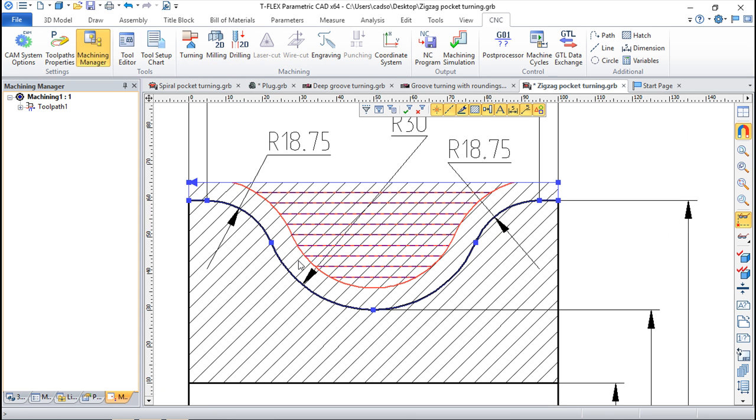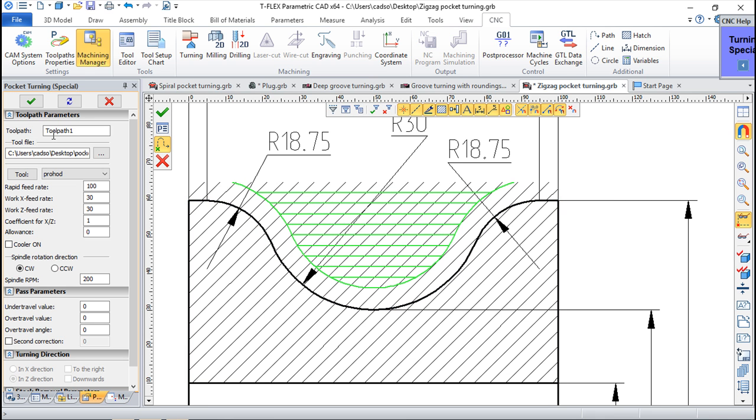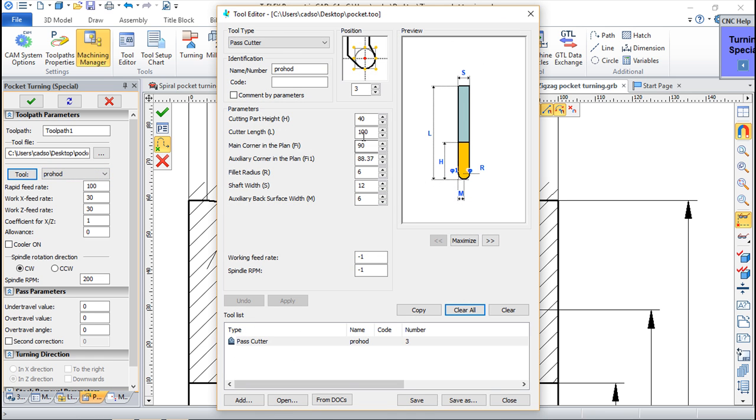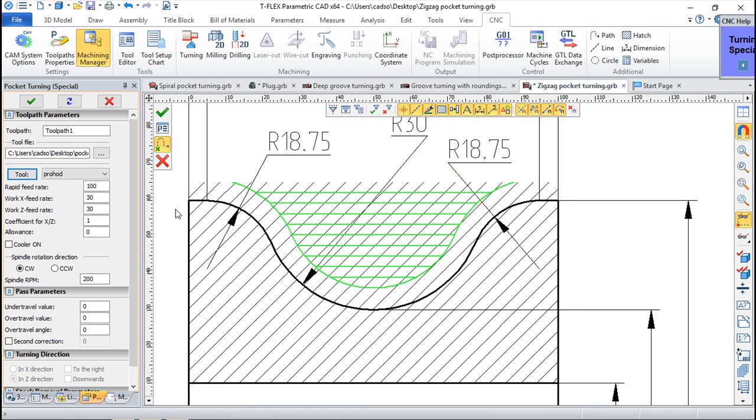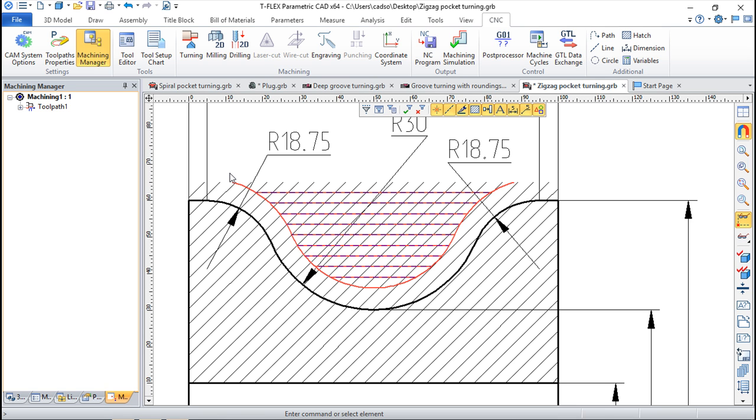It is important to understand that this difference that we see in here has to do with the tool. If we look on the tool, you see that the contact, the control point is in the middle of the tool, so that difference is the radius of the tool. Okay, if we say this point here, so the toolpath on the particular case that we are using will, because we are using 0, this particular tool will be different in terms of the calculation.